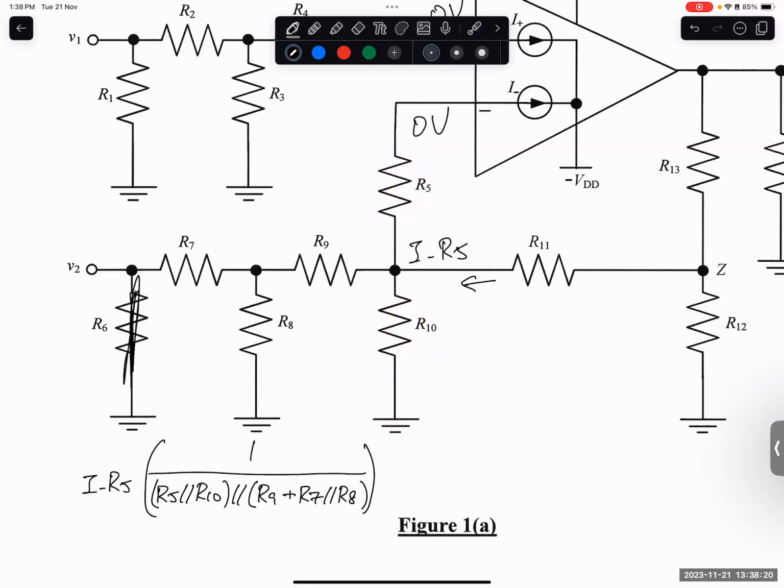Just ask, I'm pretty sure people got the same question. You take I minus times alpha, you get a voltage at this number, because there's current going through here. So why are R5 and R10 in parallel, right? Because there's current going through here, and these two are connected to ground, and you can see there's actually 3 things parallel: R5, R10, and the whole thing in parallel.